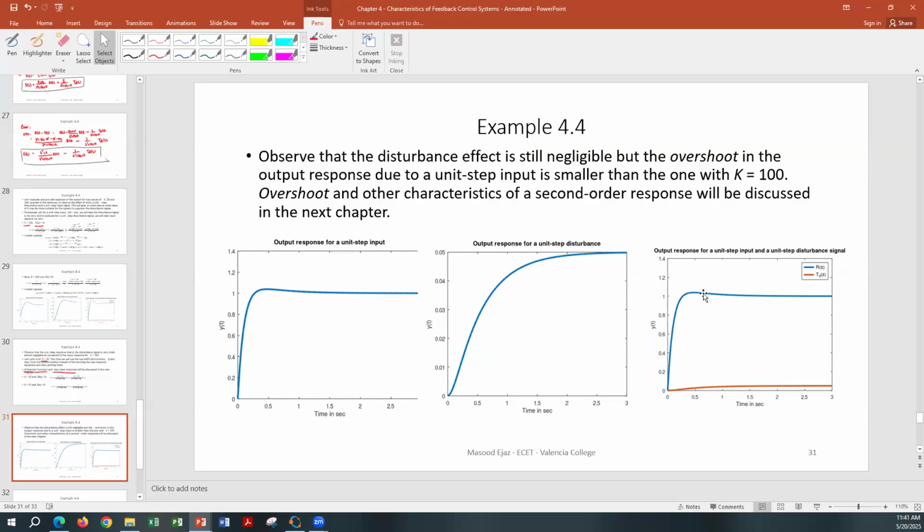And if the overshoot is not high, it just goes and then becomes kind of smooth, like in what happened in this part. It didn't rise much, and then it settles down to 1. Then your angle is not really moving a lot. The laser guidance system that you're using, that angle, the boring machine angle, is not moving a lot. And in your case, you're saying boring machine, of course, using some arm or some drill to make the bore. So in that case, yeah, you have to keep it pretty constant. You don't want to move it a lot.